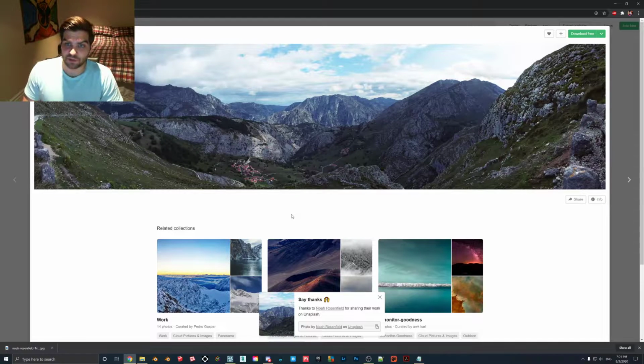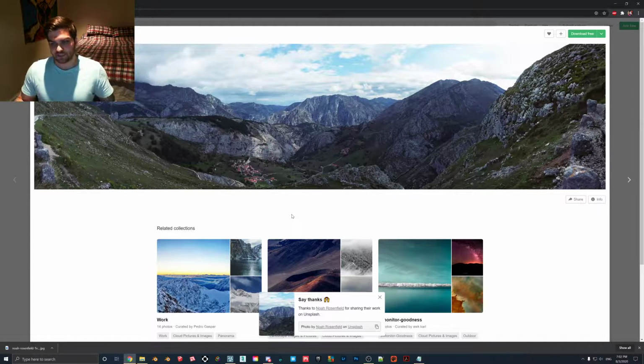The other thing that I'm going to do is, I actually figured out how to do this while I was getting this video prepared, using Blender. I actually know now how to bring in your own HDRIs into Blender. I'll show you how to make a sky sphere. I've tried to do this with SketchUp before, but it doesn't work, because in Lumion, if you bring it in from SketchUp, then you basically have this physical ball that's going to be encapsulating your scene, and then the light's not going to get through, because when it comes from SketchUp, Lumion almost thinks of that as a wall.